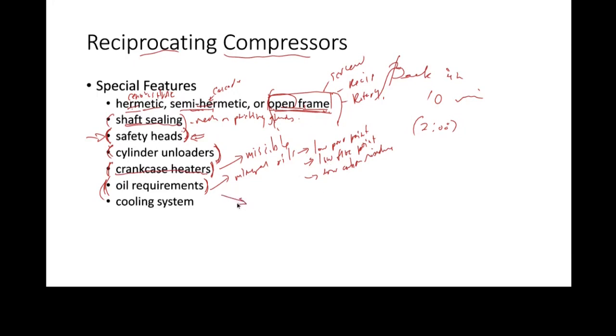But we also have, for certain types of refrigerants like R134A, other oils, polyolester oils. And so certain refrigerants require synthetic lubricants because they're incompatible with mineral oils. And so you'll hear the term polyolester oil, especially if you've got an R134A machine. There's an example of a machine that doesn't like mineral oil. It wants a polyolester oil.